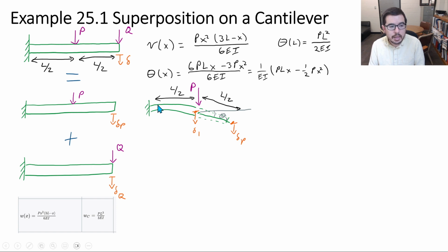The basic idea is we're going to pretend that this load P is acting at the end of a cantilevered beam. Because all this material right here is not experiencing any internal shear or any internal moment. Nothing is happening in this. This is essentially acting as a rigid member. It's along for the ride.